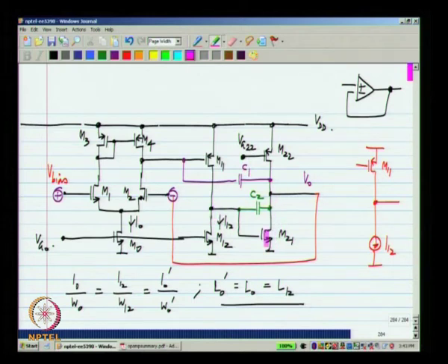This is a common source amplifier, and from there to the drain of M2, there is an inversion. So, what we have is some amplifier with a positive incremental gain feeding back to the gate of M11, and we know that this is exactly what we need. Okay. If the voltage here increases, that means that the current in M11 is too much and the gate voltage should be increased, so that it reduces, okay, and vice versa for smaller currents.